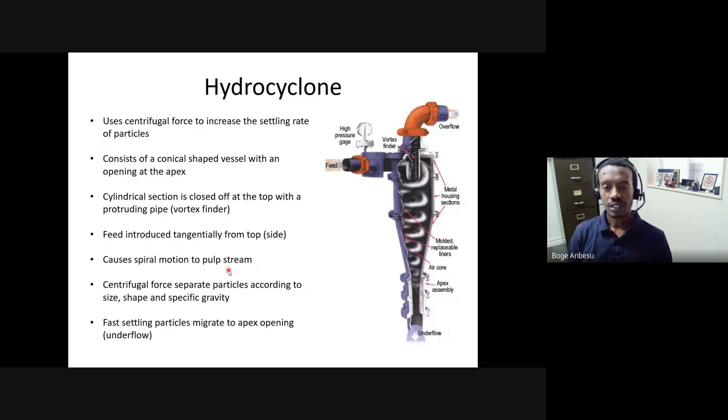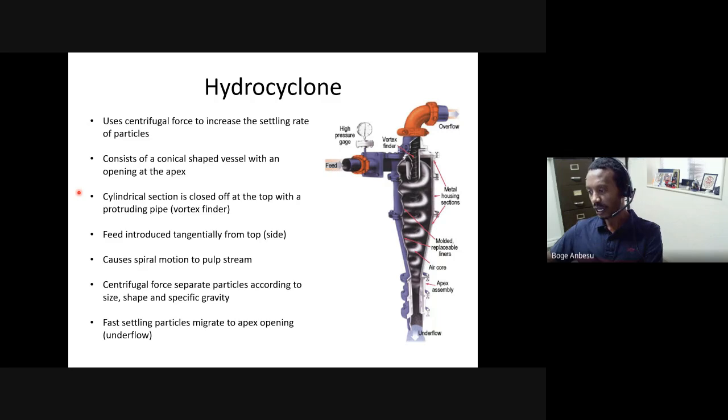So that's essentially how a cyclone works: by moving the particles inside the cyclone in a circular motion, coarser ones attaining a centrifugal force and going to the wall of the cyclone, and smaller ones dragged to the center of the cyclone, eventually exiting as the overflow stream.